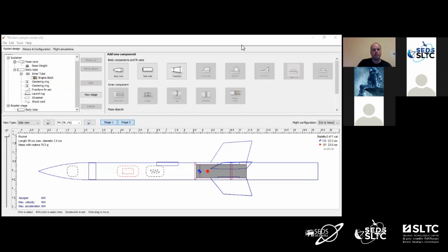It's also measuring time from liftoff detection, so it can detect when the rocket has lifted off. It's monitoring barometric pressure changes, because as you go higher in altitude, barometric pressure decreases. So the computer can detect all these things, and you've got it pre-programmed and configured so that everything is timed correctly. That's a more advanced setup.